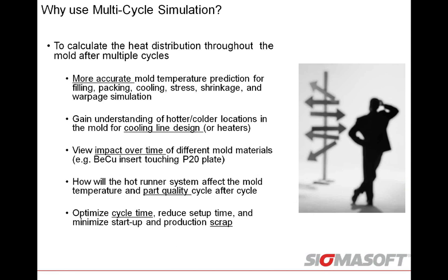So first, it's more accurate. More accurate mold temperature prediction. When we go through and predict our filling, our packing, our cooling stages, and then get into our stress prediction, shrinkage, and warpage predictions, we get a much more accurate capturing of what the mold temperature distribution is.